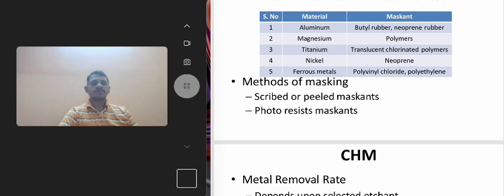After exposure, the workpiece is developed by immersing it into a tank which contains an organic solvent bath solution. The unexposed portions are dissolved out during the developing process, while the exposed portion remains on the workpiece.